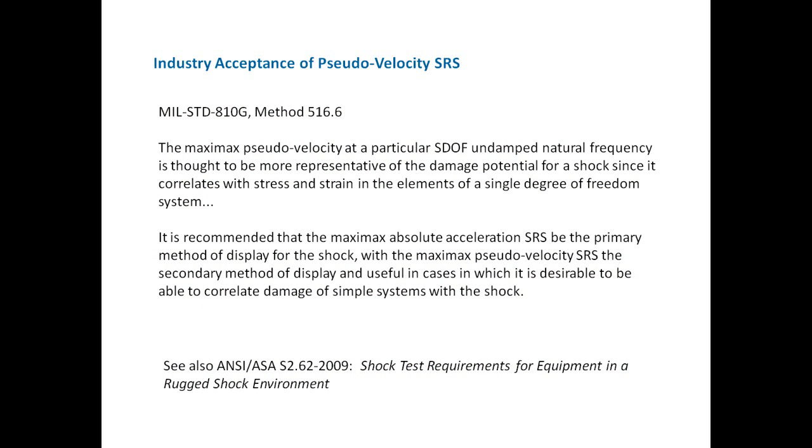I think we've kind of talked about some of these things already. Well, the pseudo velocity, which Gaberson championed for many years, he and others think it should be the primary metric for our shock response spectrum specifications and testing. And of course, getting the mil standards to change, I mean, we're talking paradigm shift here.